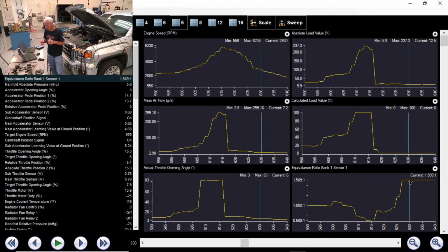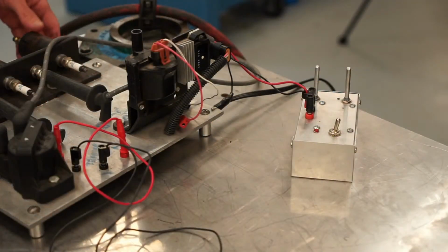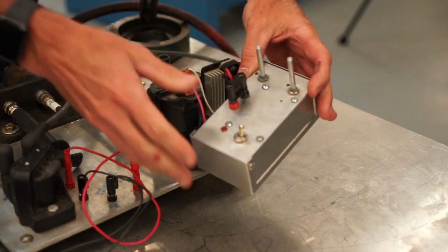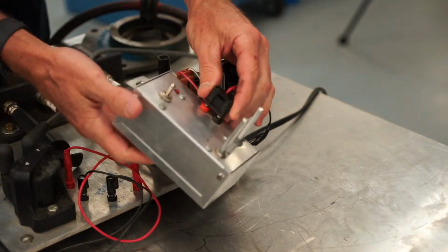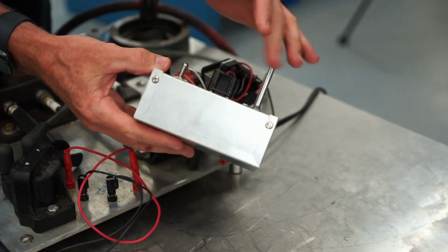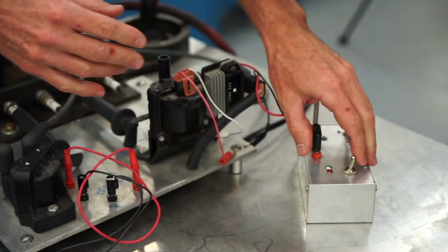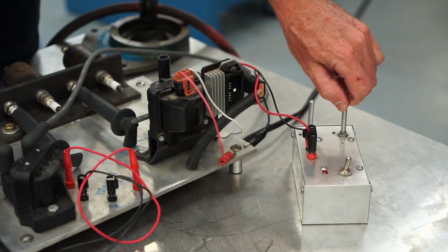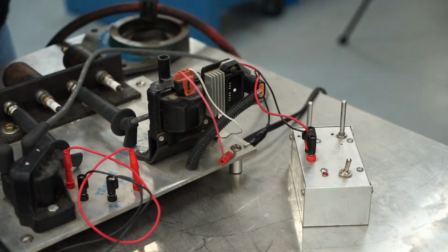Now, I was going to show you a few things on ignition using scopes. And I've got this little mock-up here. It's something I made for the sake of the class. It's called a shocker box. You can buy these things, or you can find these instructions on the internet. On the inside, there's a 555 timer circuit and all that stuff. When I flick the switch on, I can change with these dials how fast it's going to operate these coils.